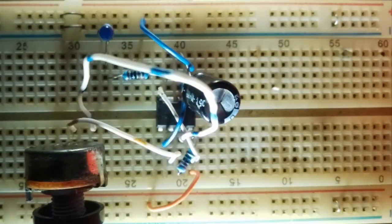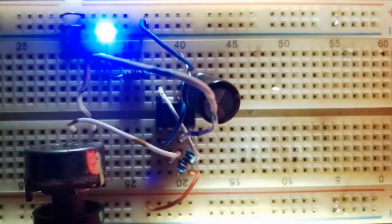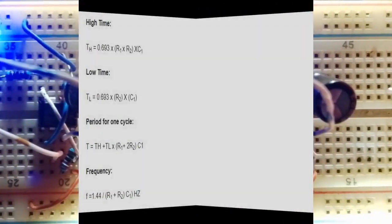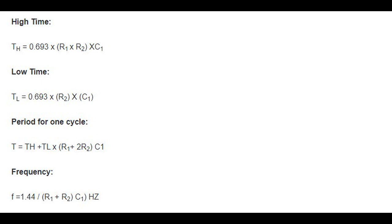But what if you want to design an LED flasher circuit with an accurate frequency of output? Some applications demand a specified frequency or time interval. No worries. You can always use the formula on your screen right now to calculate the values for a known frequency, C1, R1, and R2. You will, of course, have to make a correct guess of two parameters and then calculate the other.